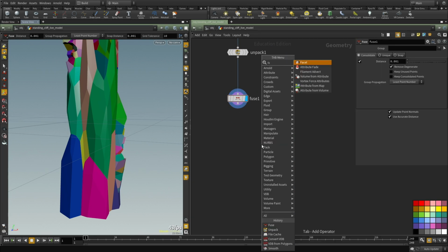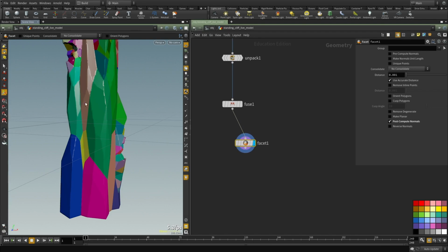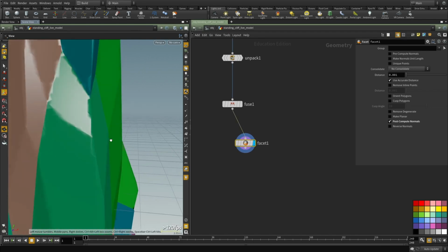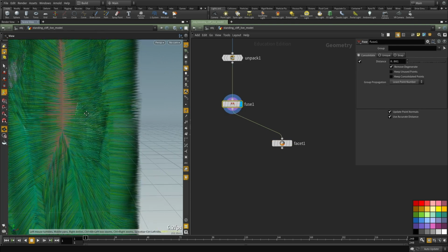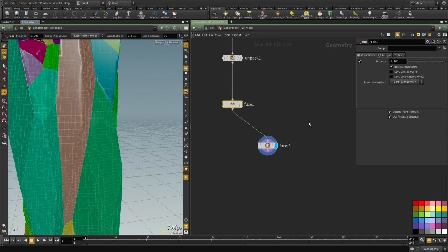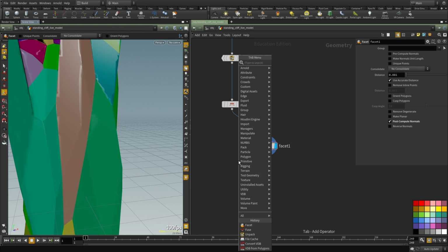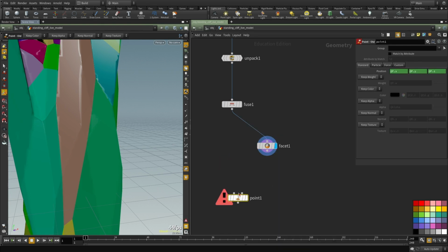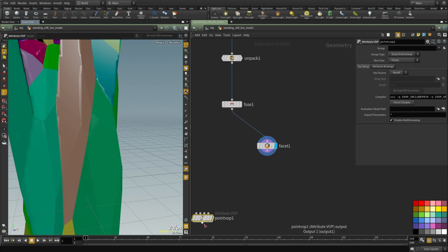and then I'm going to compute the normals, make sure that I have the right normals, and maybe I think we can leave the normals. Let's try without the normals and see, because these guys should also be, yeah, let's try both. Let's try with the normals and without and see what kind of results we can get. And then let's put down a point VOP.